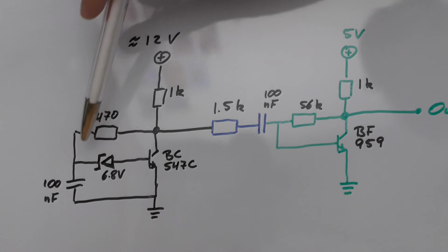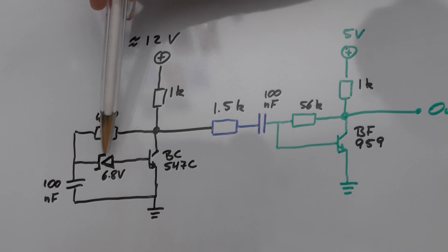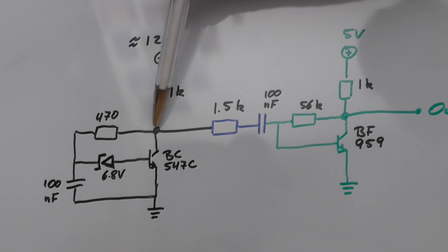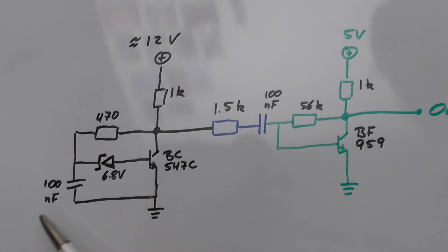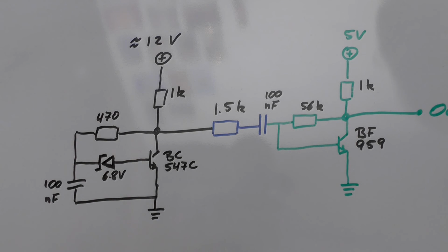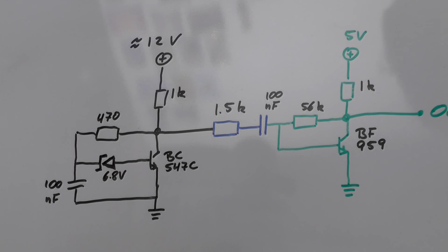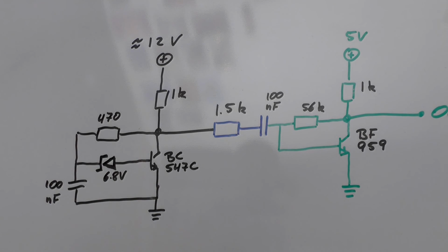Eventually the avalanche stops, and at this point the transistor goes high impedance again, and the voltage here goes up because it's connected to 12 volts through the 1K resistor. Figuring out the values, the capacitors here and here are not overly critical. The resistors control to some degree the amplitude and the frequency spectrum, and yes, I've just experimented with those, largely because they depend on properties of the Zener diode which you don't even find in the datasheet. Well, at least I didn't.